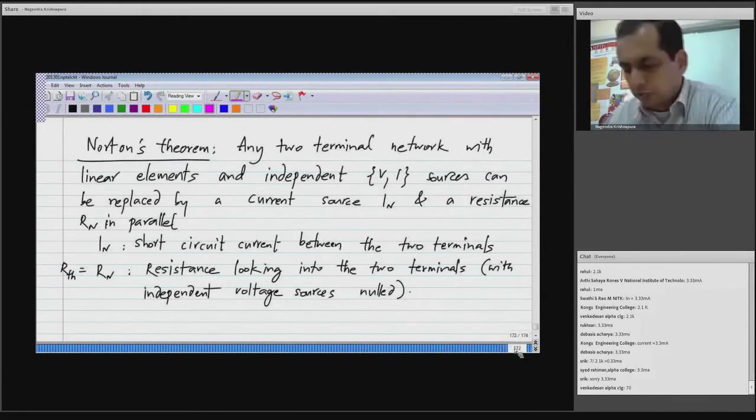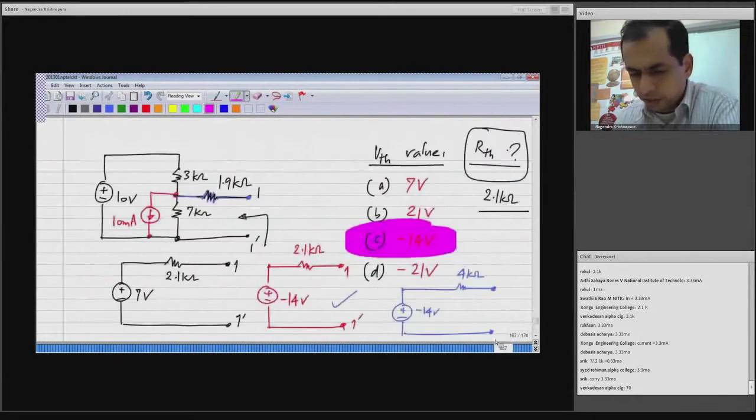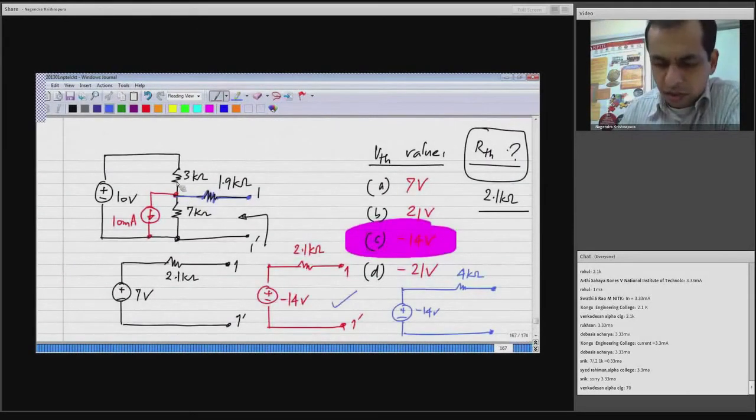Now earlier there was a question which I think was regarding this circuit, saying if there is yet another current source here, 3 milliamp, what happens? So this is quite simple. This 3 milliamp and 10 milliamp are in parallel. It is like having just a 7 milliamp current pointing downwards. So instead of 10 milliamps, you have 7 milliamps.